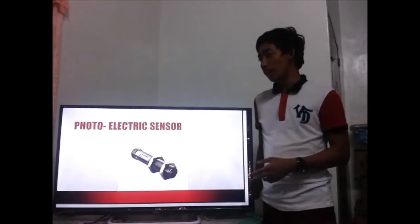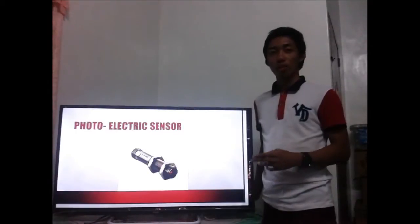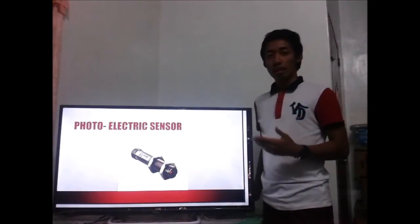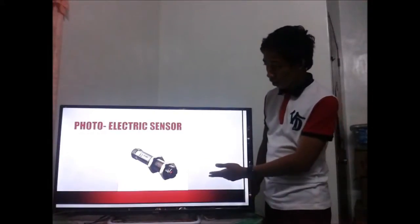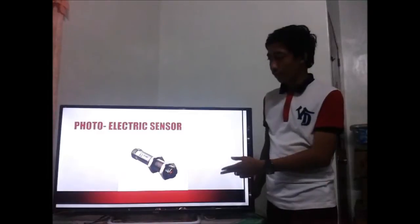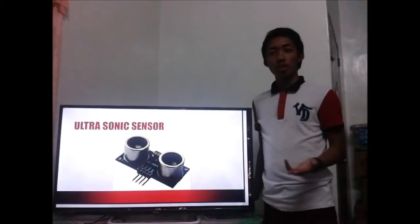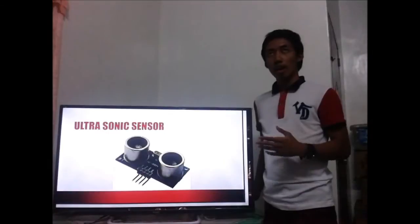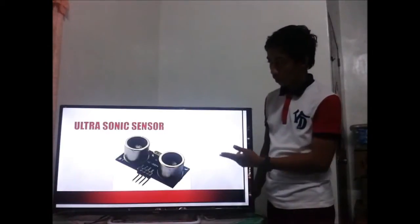The next one is the photoelectric sensor. The photoelectric sensor is another type of positioning sensing device. The photoelectric sensor uses a modulated light beams that is either broken or reflected by the target. This is the example of photoelectric sensor. Next is the ultrasonic sensor. Ultrasonic sensor use a transducer to send or receive high-frequency sound signals. This is the example of ultrasonic sensor.